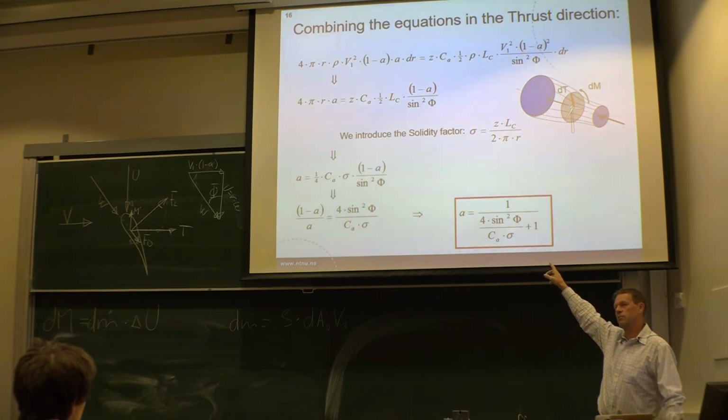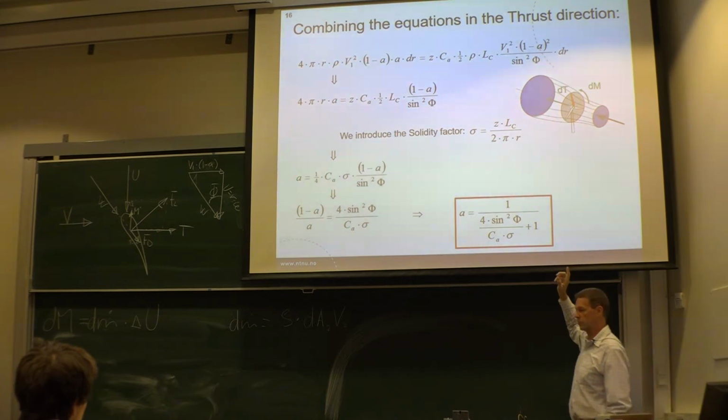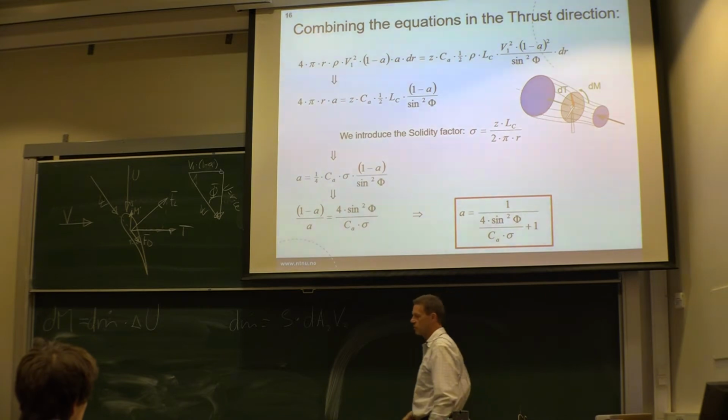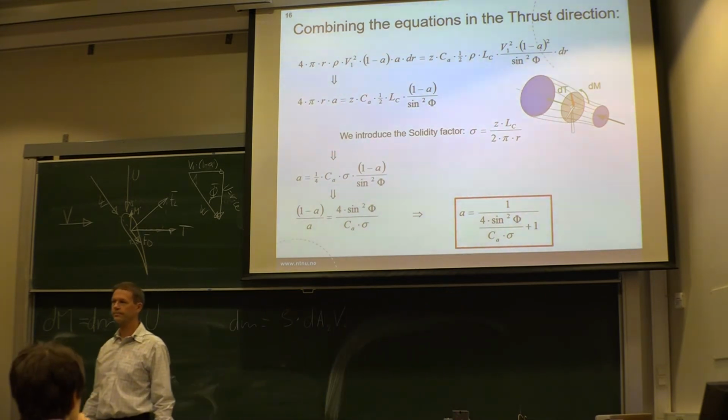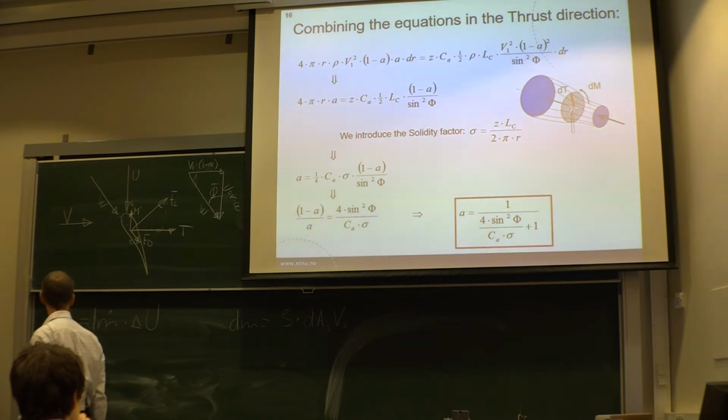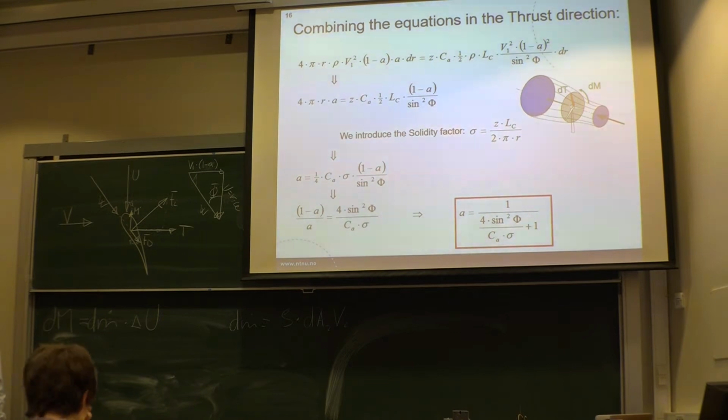This is the point, because now the blade element momentum method is actually going to find the value for the induction factors for you. And once you have the induction factors, you have the triangle. And when you have the triangle, you can go on and find the CL and CD, the lift and drag coefficients, and so on.